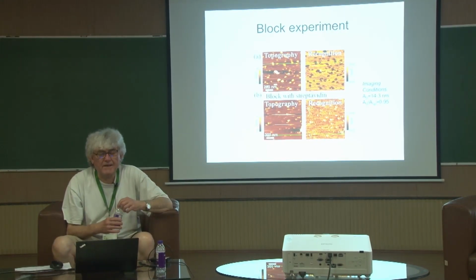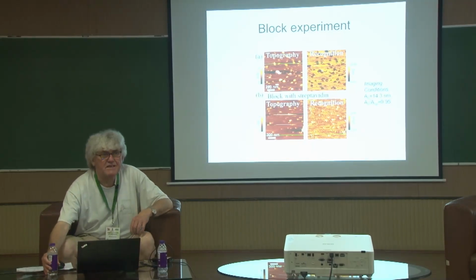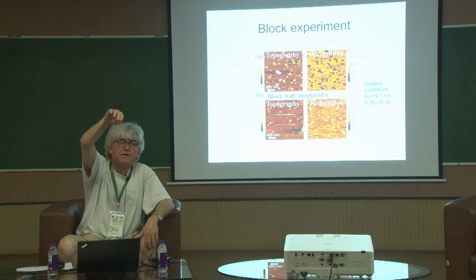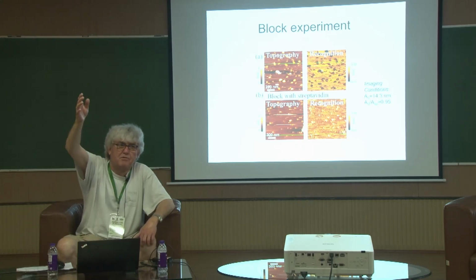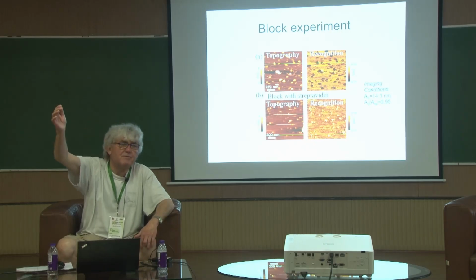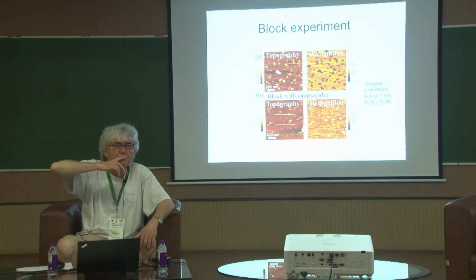So I would think actually it's an advantage, because if you image a moving structure with a conventional AFM, then you just see it blurred. And with the high-speed AFM, you have a much better chance to get a sharp image because you image faster and even detect the movement. That's how I would see it.